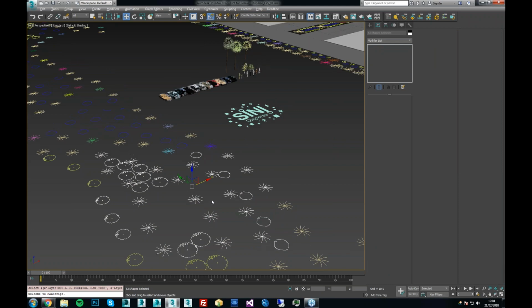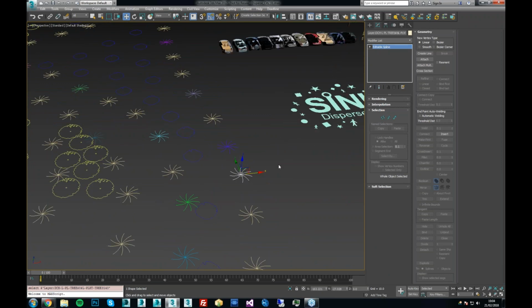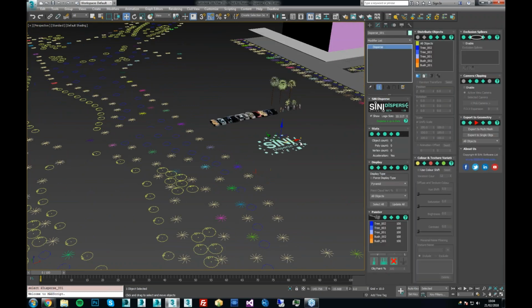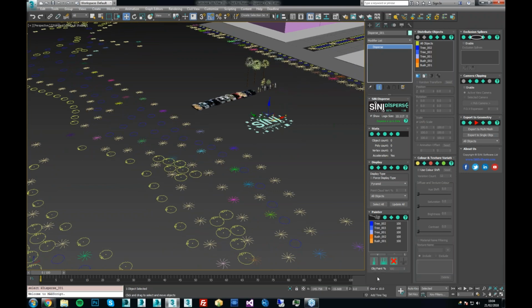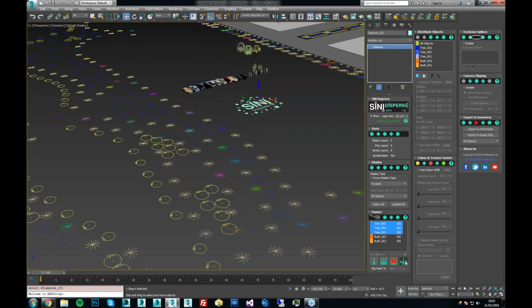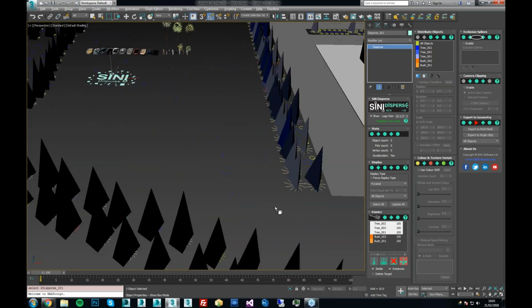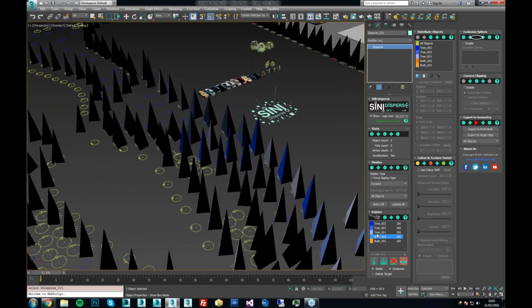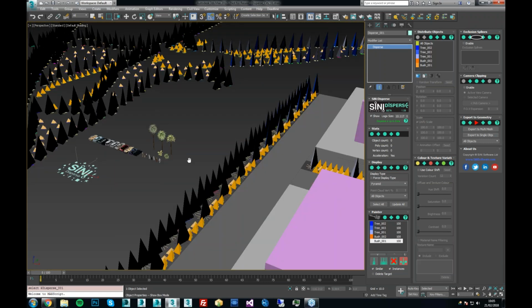What I have in my scene here is a whole bunch of CAD symbols that we took and exploded into different objects. As you can see up in here, none of them are instances. So Disperse will go and find stuff that's similar in its replacing method. Down in our Painters tab, we have paint as a single object, paint multiple, or erase. We also have this last button, which is replace object. If you have something selected in your scene, you'll see it enable. Now I can simply press that button and select a symbol that I want to replace, and it'll replace those objects in the scene. Same thing going down, selecting a bush, I can select another symbol, or the second bush and select the third. It's as simple as that to replace objects in the scene without painting them.